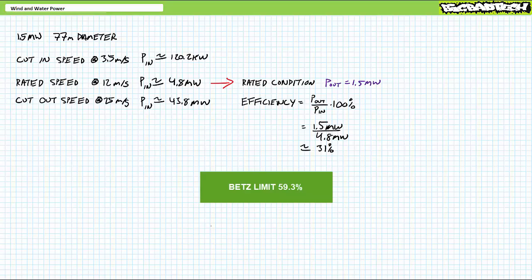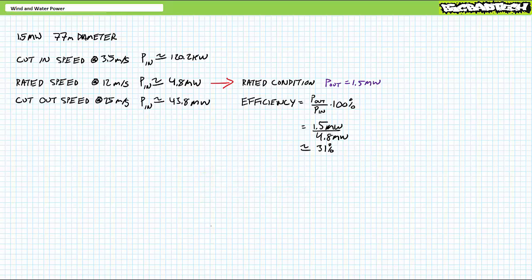turbines cannot overcome, principally because extracting any more than 59% of the available power from a column of air would essentially stop the air from moving through the rotor-swept area as more and more dead air particles pile up behind the turbine. So 31% is actually a pretty respectable efficiency, especially considering wind is free and doesn't pollute the environment if you let some slip through your grasp. The same cannot be said for gas engines, which typically have an efficiency of only 20 to 40%. Not only is gas expensive, the byproducts of combustion take a toll on the environment.